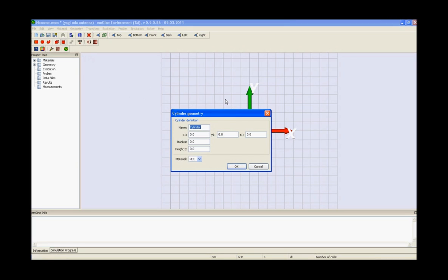The next step is to design a reflector of cylinder for the modeling of wire-type Yagi Uda antenna. This can be easily achieved by creating a cylinder made up of PEC material and entering the proper transversal coordinates.